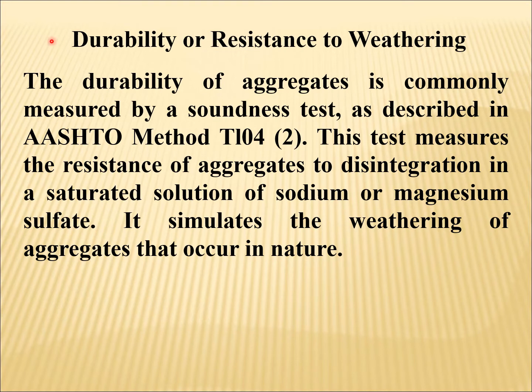Then comes durability or resistance to weathering. The durability of aggregates is commonly measured by a soundness test, as described in AASHTO method T104. This test measures the resistance of aggregates to disintegration in a saturated solution of sodium or magnesium sulfate. It simulates the weathering of aggregates that occurs in nature.